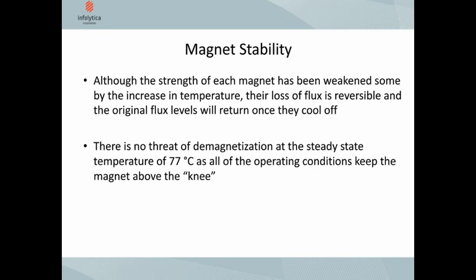And the other thing to note is that although we have lost some flux density due to elevated temperatures, we do know that if we were to cool off the magnet, then the flux loss is reversible and the original flux levels would be returned to the magnets.